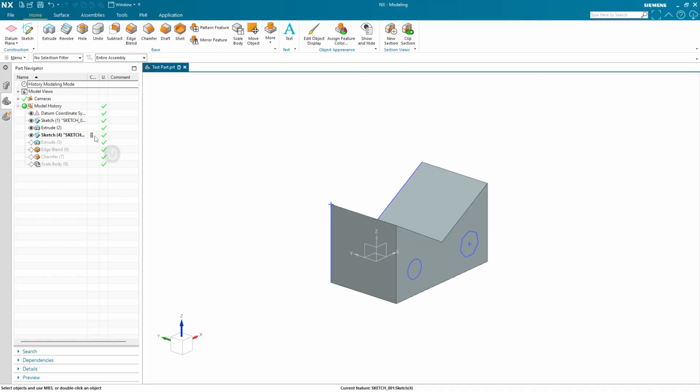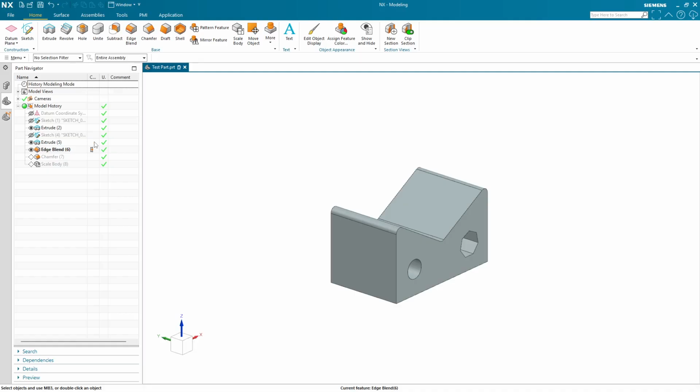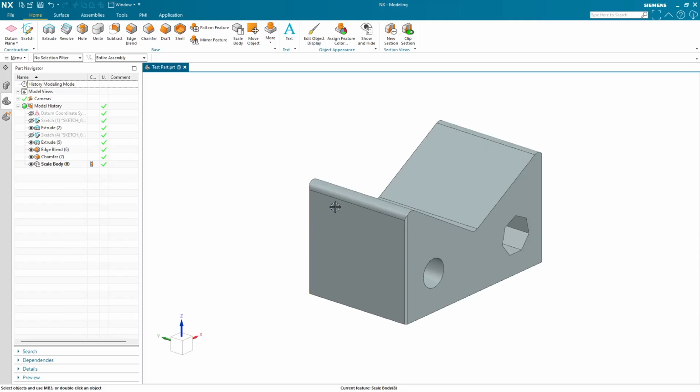So this is really useful if you got a little lost, a little too deep in modeling. You need to go back and see how something was. Maybe something broke. Maybe you realized something. If you need to go back to a previous state in this part's lifetime, according to this tree, you just click up and down, and it'll give you that stage in the modeling process. It's a very, very handy tool, very commonly used across all CAD softwares, and something that you should really get